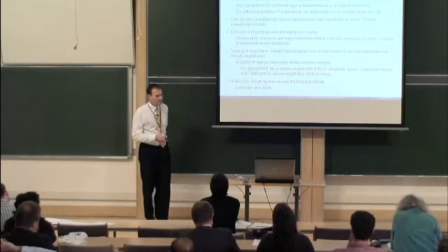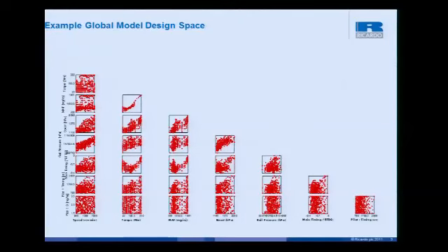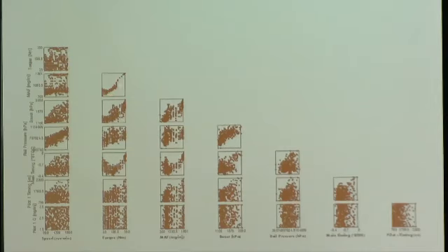And then finally, design space. Design space is often very non-linear. So this is an experiment with speed, torque, MAF, which is used to control EGR, boost pressure, fuel pressure, main timing, pilot timing, and pilot quantity. And you can see that the runnable range, the same MAF, can be very narrow depending on the speed and the torque, and possibly the setting of other variables too. So this means that trying to apply central composite designs or Box-Behnken type designs is not really appropriate for this type of application.